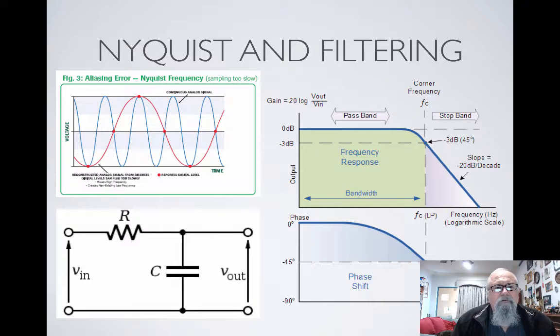So in this case, if we look at the signal in the bottom left corner, we have a resistor which is set to define our corner frequency, and a capacitor which will shunt high frequency signals down to ground. This way it limits the upper frequency components that can actually get into our system. It's a very simple sort of filter, but it's quite effective in limiting some frequencies.